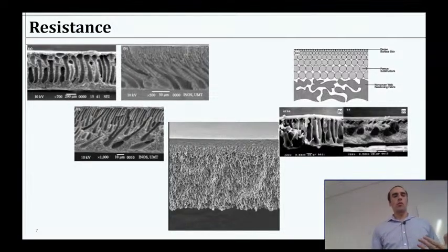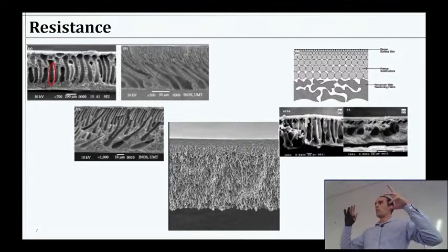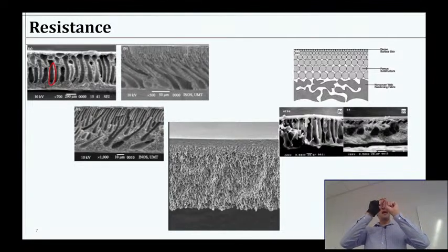You can see that effectively what you have are larger pores to allow water to flow as easily as you can through where you just want a supporting layer. It's almost going to be like a sponge or something. And then at the edge of it, you want a really thin separation layer, the thinnest you can, while also being sturdy, right? You don't want it to break and let larger stuff through. So you want a very porous area through here, and then a very thin and sturdy, supported separation layer.